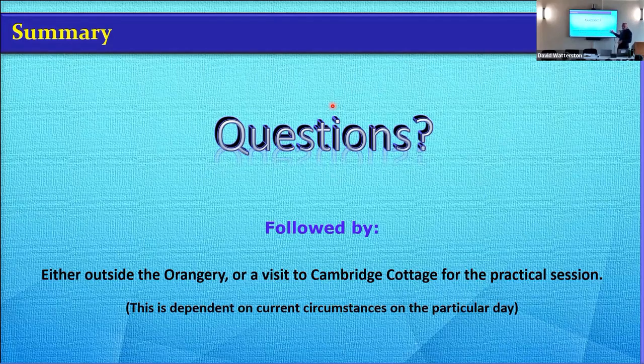So if you got a cheap price for doing a drone survey or a scanning survey, well, you wouldn't know it's cheap, would you? But you could ask the question, what is your control based on? How are you doing the control? Because if they don't have a survey instrument, a total station theodolite to take a millimetre and a second of arc, and some good device to measure between there to there down to the millimetre, it's not ground control, it's not survey control, it's not survey quality.